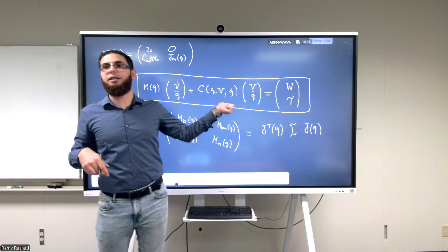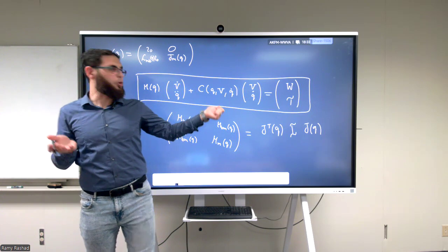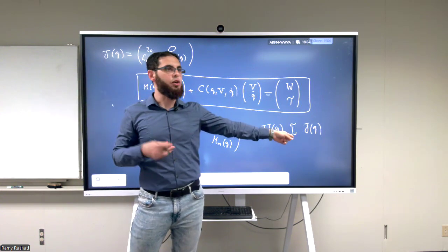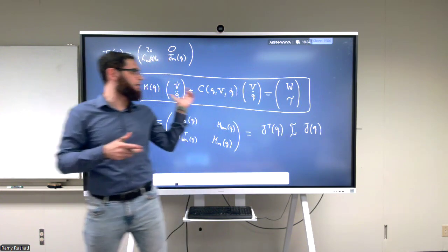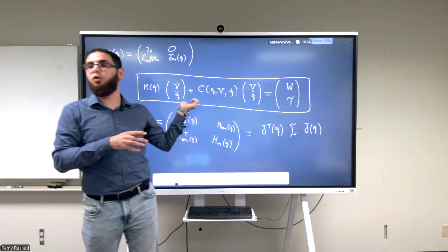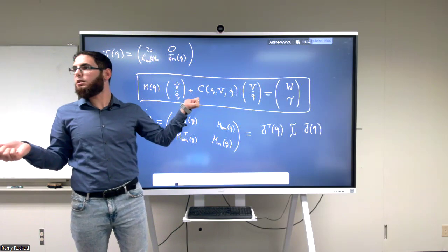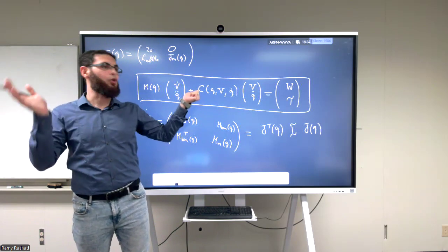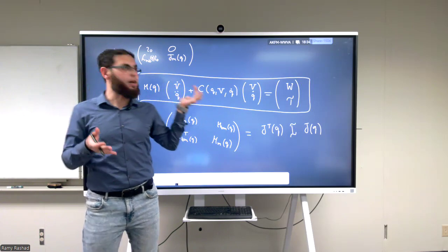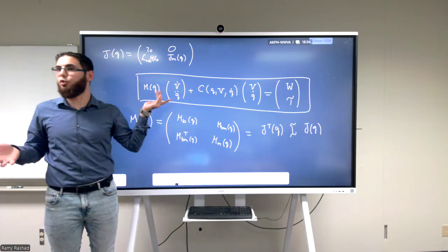This is exactly what the URDF file that you build does for you, because in the end, you tell it all of the inertias, you tell it all of the joint transformations, and it will calculate this. It will calculate everything you need inside. The simulation of this is exactly what Gazebo does, or Isaac Sim or NVIDIA or whatever. They just have smart ways of transforming this into something on the computer.